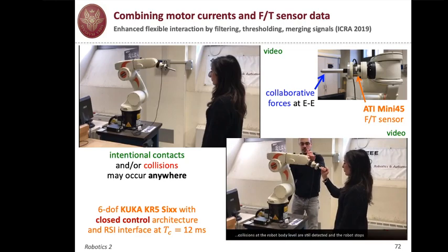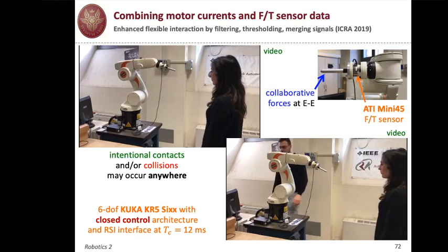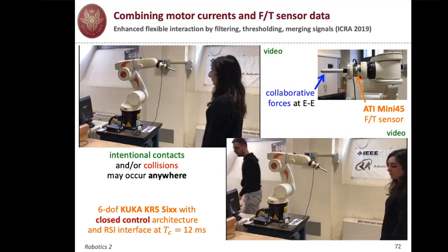So you can move around the robot by holding its nose, with the force torque sensor feeling the contact, and then the robot may hit some object or another part of the human, or another human coming and stopping the robot by hand, and then this supersedes the collaborative part, still in the principle of the hierarchy of safety: safety is the most important, then coexistence, then collaboration, in a coherent way.